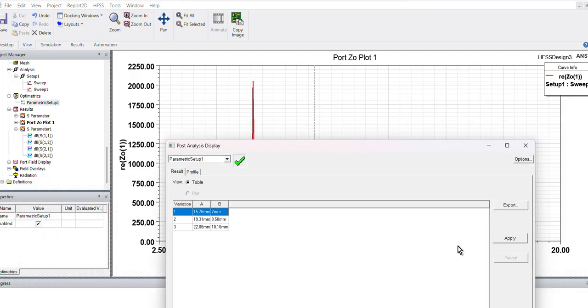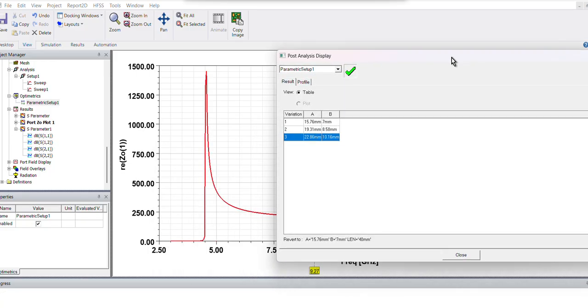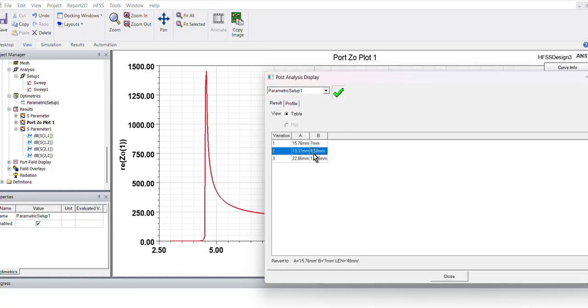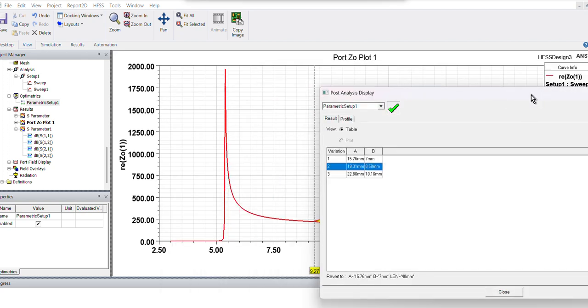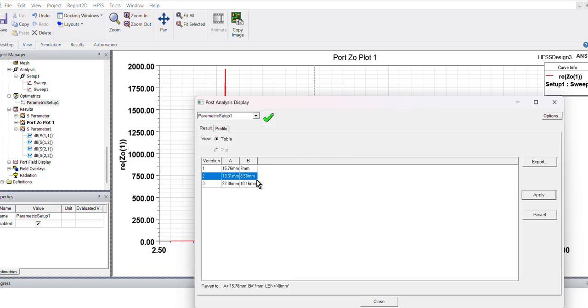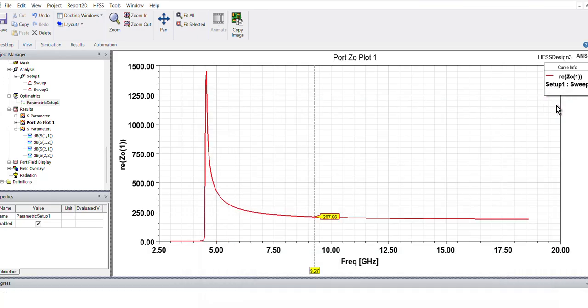Okay, so this is the one, and this was the earlier one. So your cutoff frequency we are bringing down, but because we are maintaining the B by A ratio, we are able to maintain the impedance of the dielectric filled waveguide. This is around the same range. Beautiful.